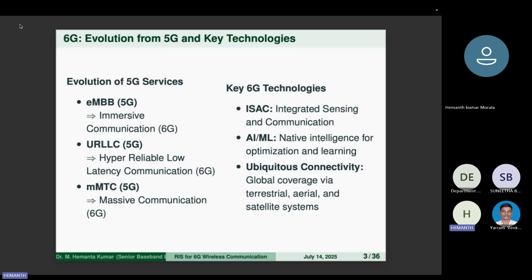For 5G you can use 15, 30, 60, 120, 240, and 480 kHz. Why are you going from 15 to 30, 30 to 60, 60 to 120, 240, 480? These are required. If higher data rate is required, then you have to go to higher subcarrier spacing. Clear? That's why it is called NR. NR means it supports all subcarrier spacings, compared with 4G. That's the major difference between the LTE system, 4G, and 5G.